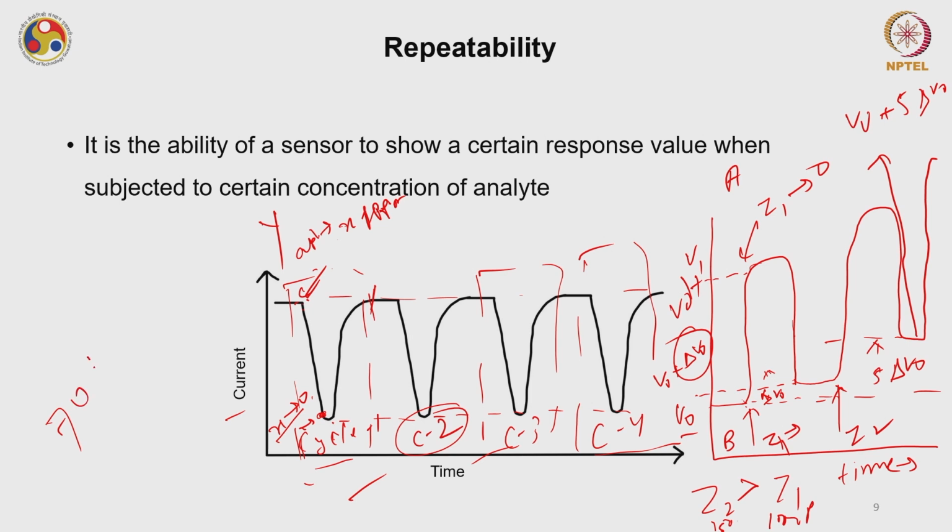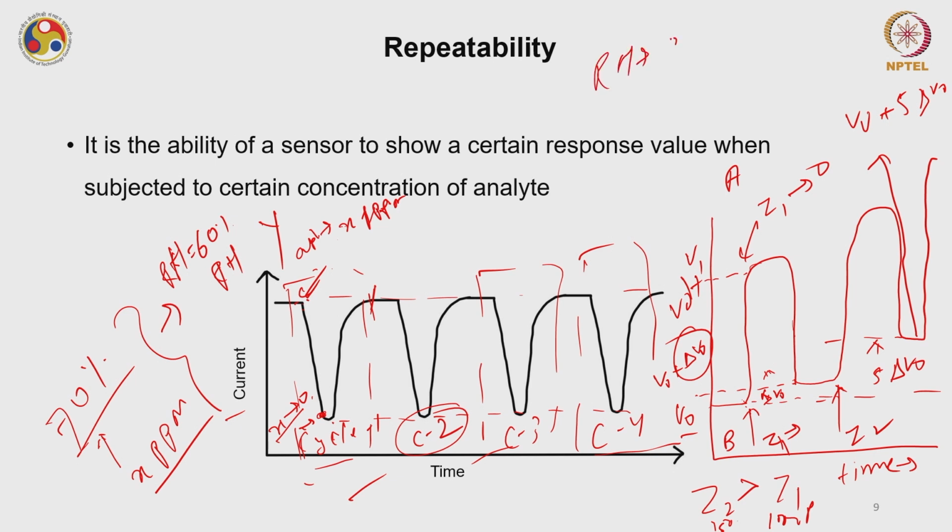So, if my sensor has a response of, say, 70% for a concentration of x ppm in a city of India where the humidity was 60% RH, and I test this device in another city where the relative humidity is very high, say 98%, a reproducible sensor may retain this response of 70%, because it may have only minimal effect from ambient factors, again for x ppm only.